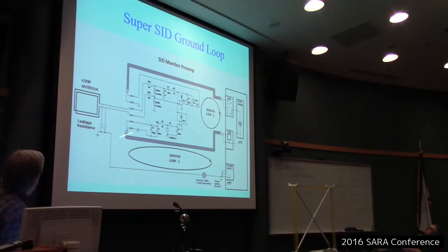So you get your cable running out here, where this cable might be a substantial length from a computer that's inside and a SID preamp outside at the antenna. And you definitely have a potential for a ground loop here, where you've got a voltage from the garbage inside the computer, and it's trying to go to this ground, and this ground is hooked to this ground inside the board, goes back here.